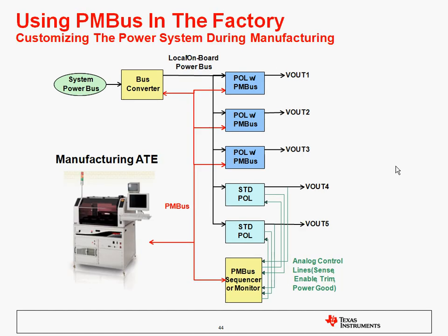The other way people use PMBus is in the factory. In some cases, they want to be able to program each and every one of these devices to a certain personality or application profile before the board is really powered up. So this can be done in the ATE stage when the board is going through its bed of nails testing. The ICs can be pre-programmed before being populated onto the board, but the important thing is that it's programmed somewhere during that manufacturing process.